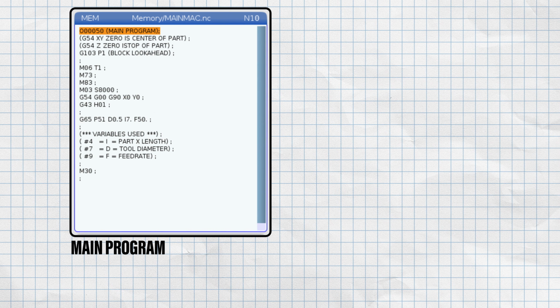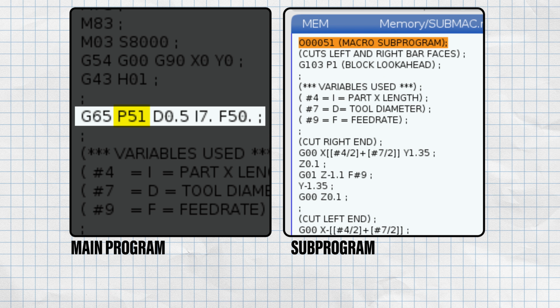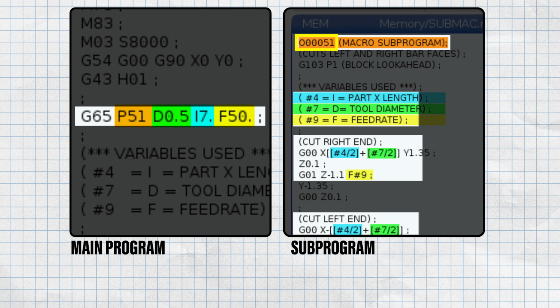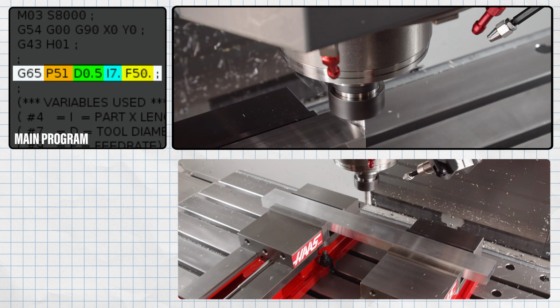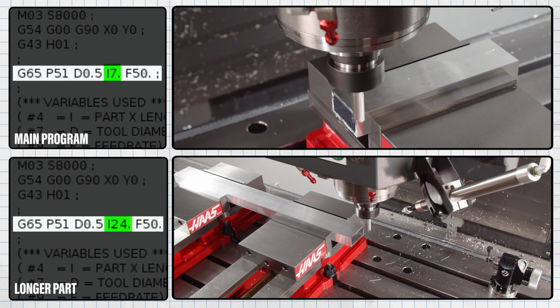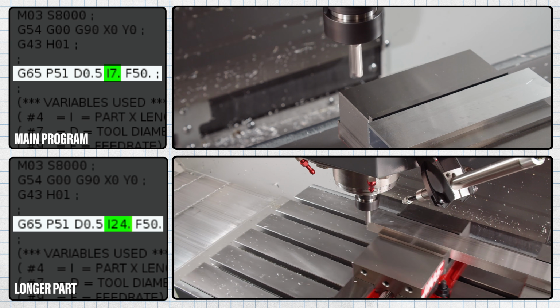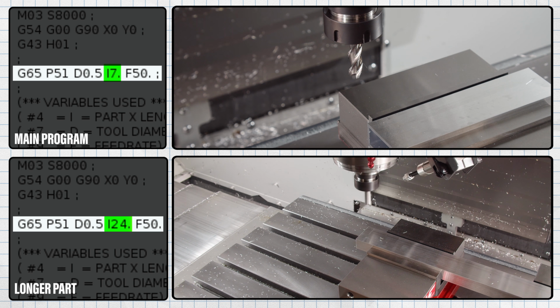On our left is our main program, which uses a G65 P51 to call up our O51.NC program. By entering our needed inputs into our G65 macro call, our subprogram will have all of the info it needs to update our toolpath and run this part. Now, when we ask to make a longer part, all we'll have to do is adjust a variable on our macro call, press cycle start, and we are machining. The macro subprogram makes all of our adjustments for us based on these inputs.